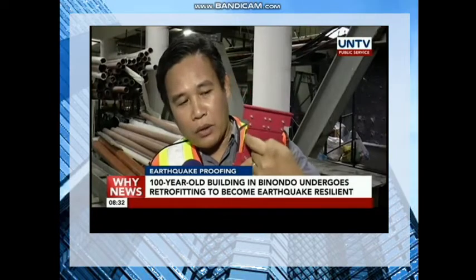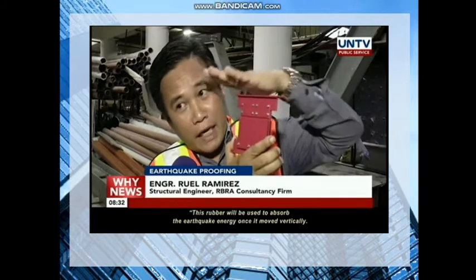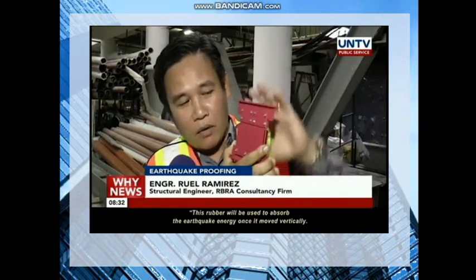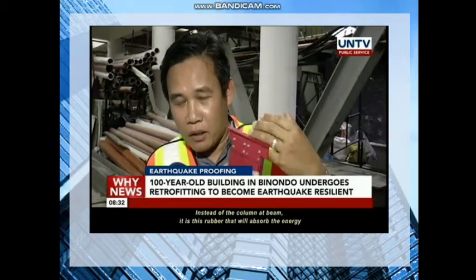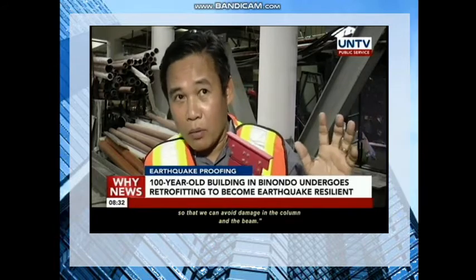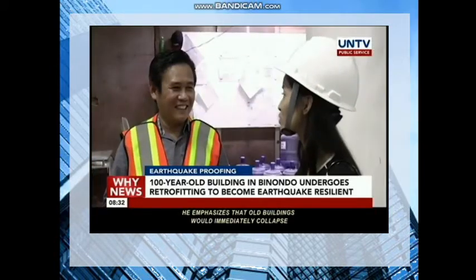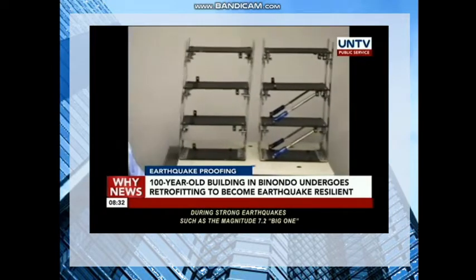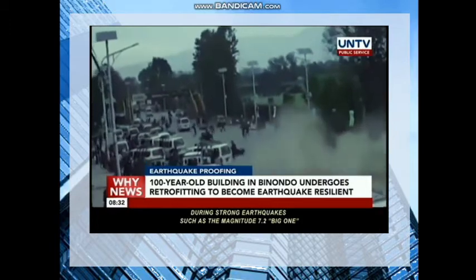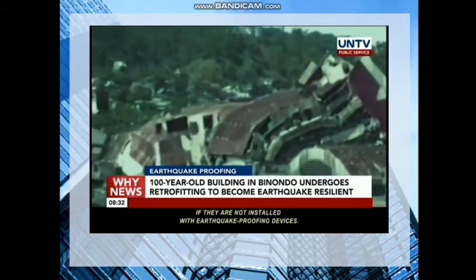This rubber will be used to absorb the earthquake energy when the earthquake moves like this. Okay? Now, instead of the column and the beam absorbing the earthquake energy, it is this rubber that will absorb the energy so that we can avoid damage in the column and the beam. He emphasizes that old buildings would immediately collapse during strong earthquakes, such as the magnitude 7.2 Big One, if they were not installed with earthquake-proofing devices.